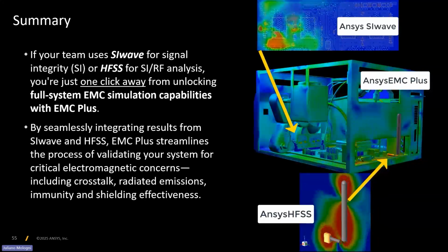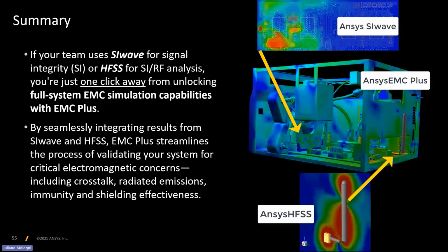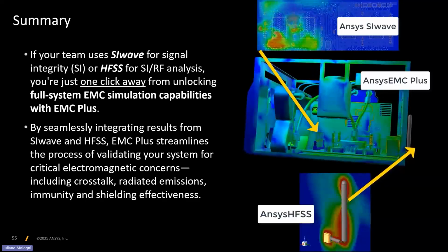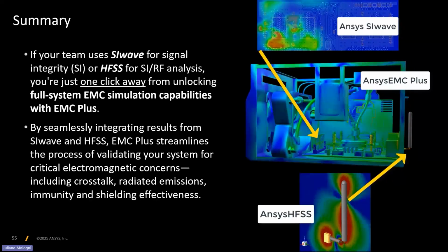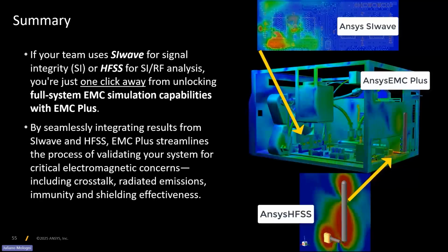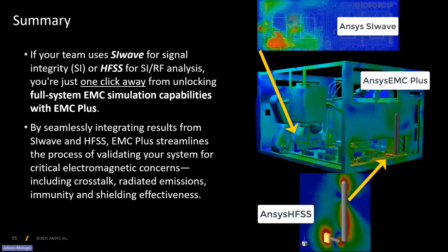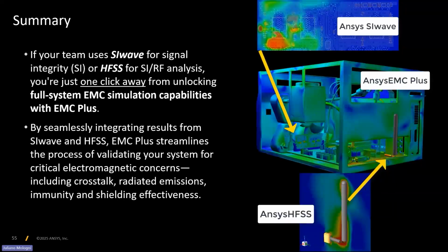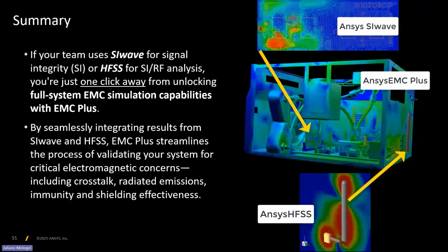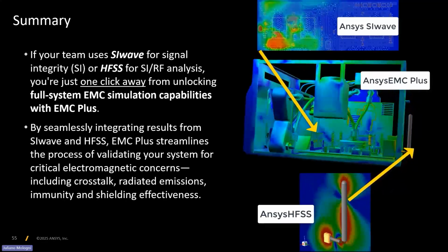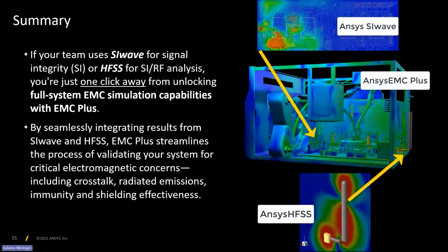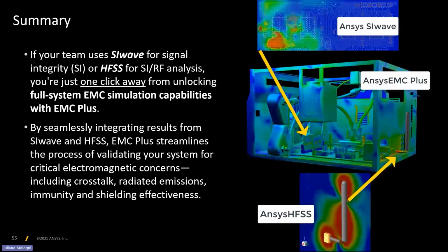We have many DC-DC converter simulations, and now with electrification, drivetrains, buck converters. Basically, you can actually add those SPICE models for the switching devices in SIwave, but usually what we do is place ports in there, sinks and sources, and then we bring that into Circuits. We even ship some silicon carbide models from ST Microelectronics and Infineon that are widely used in the automotive industry. And we have an example in here.